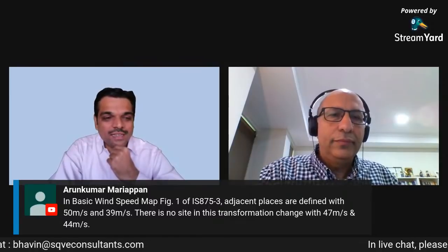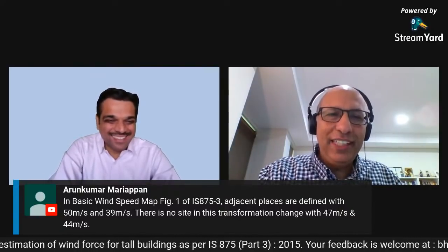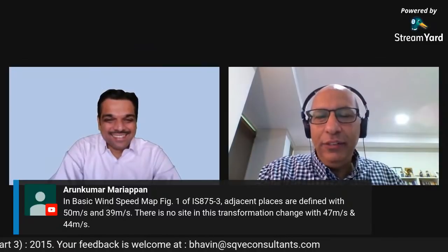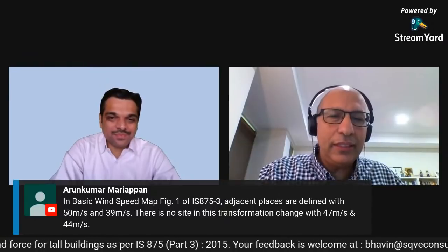What is the question? In the basic wind speed map of IS 875 Part 3, adjacent places are defined with 50 meters per second and 39 meters per second. I find that strange myself, actually. If you were to do a wind tunnel test, we don't have to use the same wind speed map. We use our own analysis, and we know that it's not that dramatic, but it's maybe for the sake of simplicity. But we know it doesn't happen like this.